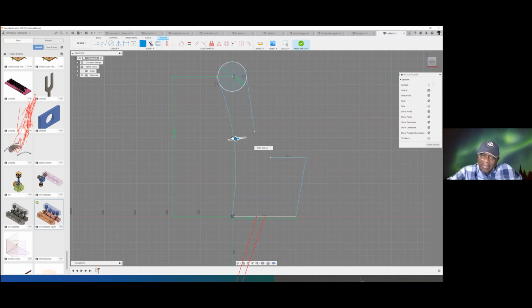I can decide to make the fillet radius small or big. So let me make this fillet radius big like this. Okay, let me make it 600. What this should be exactly, you probably can do by going to do your measurement.